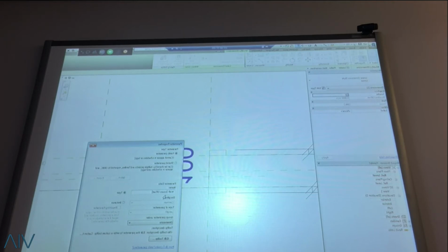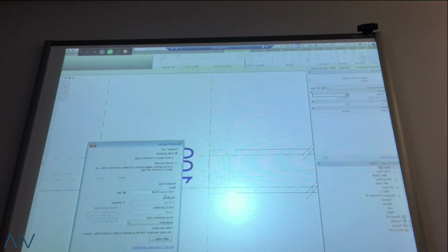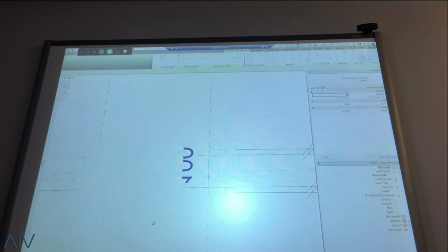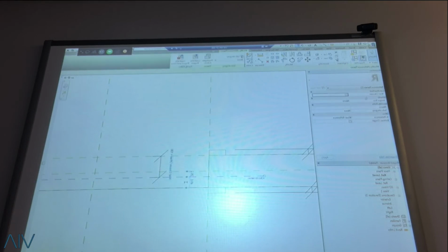But for most cases, if you're building a family, I always like to be very descriptive so that the user understands what it means. Because in most cases, I get a lot of parameters, x, y, y1, and all that stuff, and I have no idea what that does. Just be aware of that. Now, once I added that in, there's an option in here. You see there is one called the wall closure. If I click that on, now you have another one: weak reference, strong reference, and not a reference.